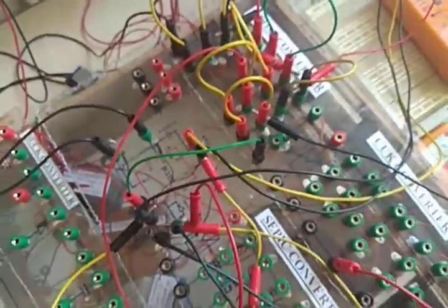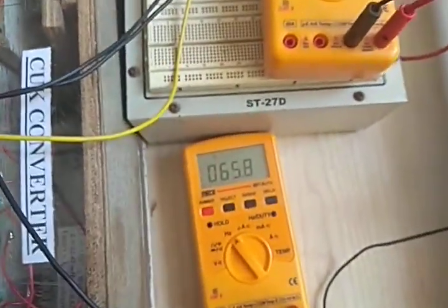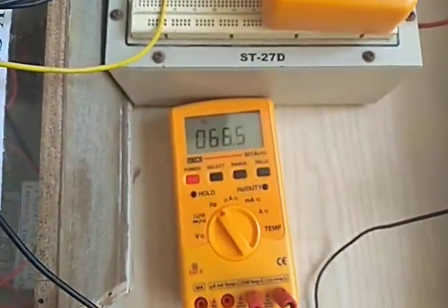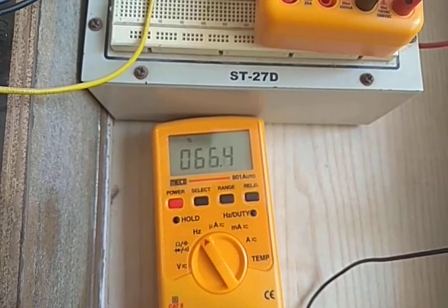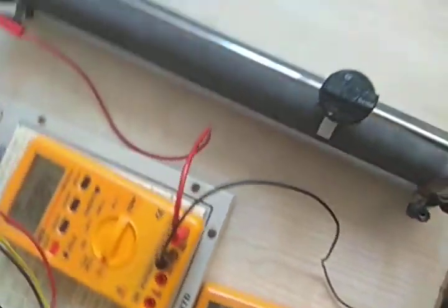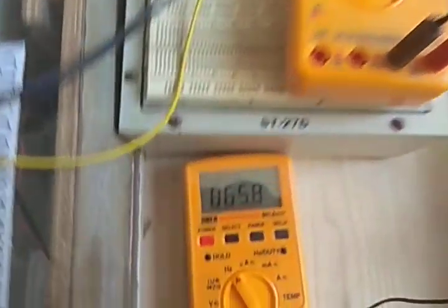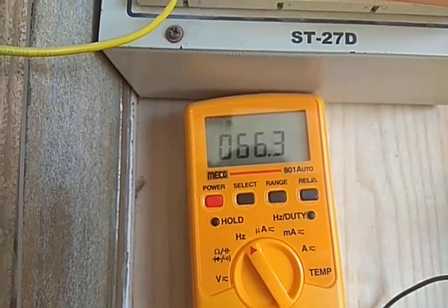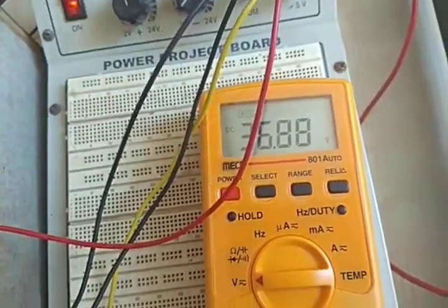Okay, so now varying the load. On the variation of the load, the duty is going to change. Previously, for RL approximately 30 ohm, the duty was around 55%, but now the load is increased, as you can see by sliding the slider. Duty is around 66%, or hovering around 65%.